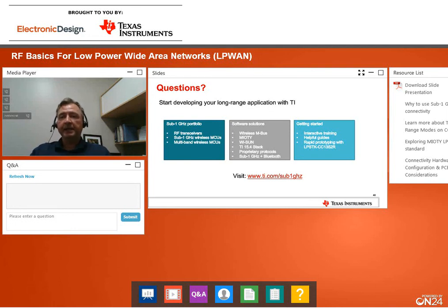And for many applications, we are proposing frequency hopping narrowbands. But for some other applications, especially from a software perspective, we do understand that it is easier to be compliant with a wideband 500 kilohertz one, because then frequency hopping is not required, and this reduces the software complexity.